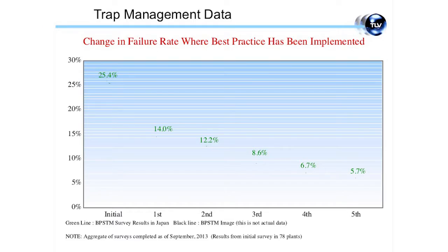We're not looking at the other benefits of better reliability, better availability of plant, and more effective heating. So on top of that, maybe every shift we could do one more batch process. The reason we came up with less than 6%: we have experience over 15, 20 years, and these are actual figures where we've looked at the first survey failure rate down to after 5 years. By trying to optimize the steam system, by looking at the bigger picture, rather than just repairing the steam traps that have failed, trying to work out why they failed, how we can make the system better.